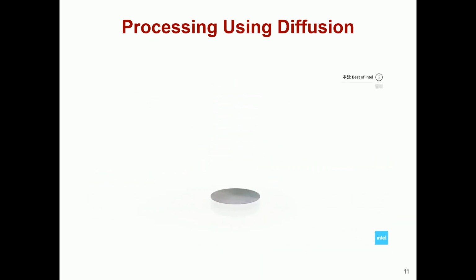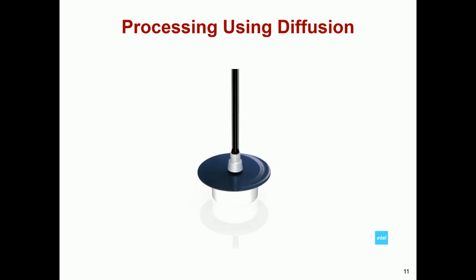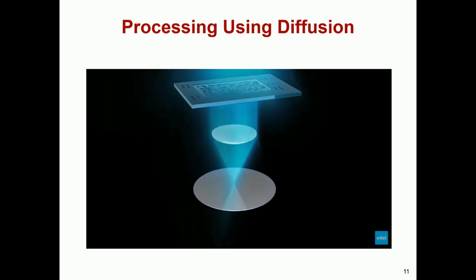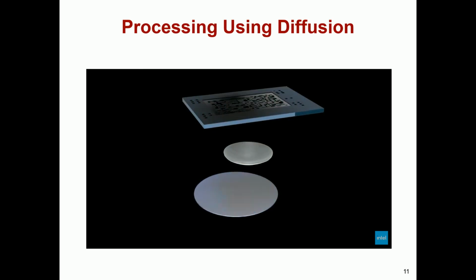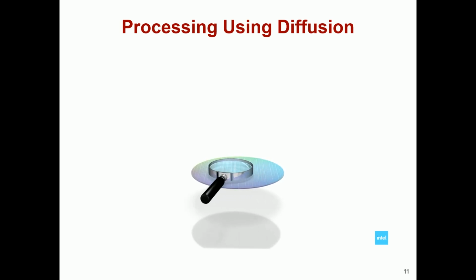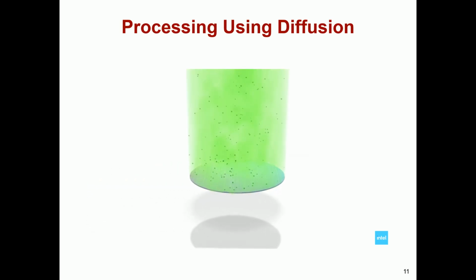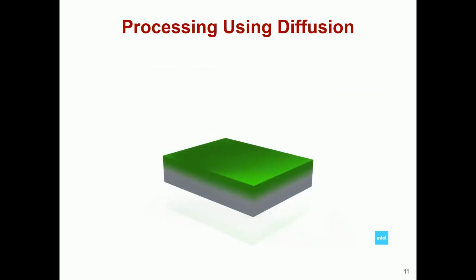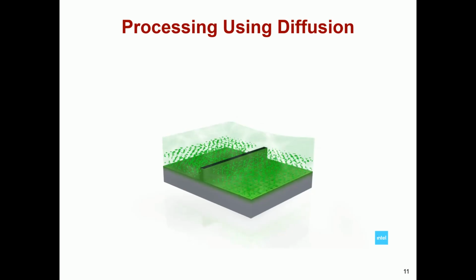Once we have silicon wafers, they undergo numerous processing steps. For patterning, we use a photoresist process. A pattern mask is illuminated with UV light through a lens, projecting the microscopic pattern onto the photoresist coating on the wafer. After developing the photoresist and etching, we create a pattern where the masked region remains protected while the unmasked region is etched away. This process is repeated many times, building up complex three-dimensional structures layer by layer.